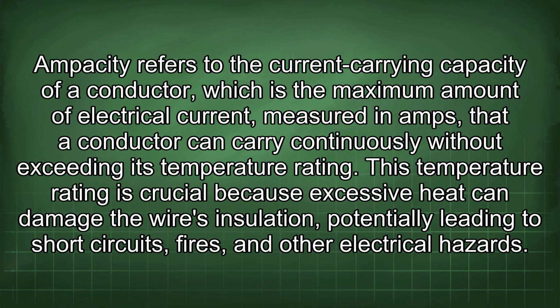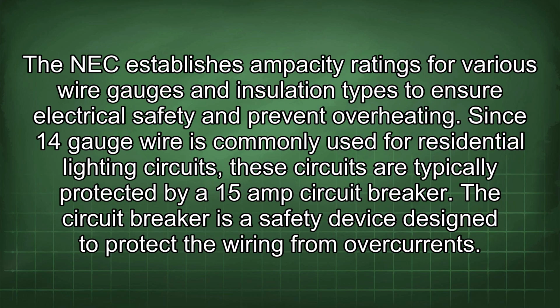Ampacity refers to the current carrying capacity of a conductor, which is the maximum amount of electrical current, measured in amps, that a conductor can carry continuously without exceeding its temperature rating. This temperature rating is crucial because excessive heat can damage the wire's insulation, potentially leading to short circuits, fires, and other electrical hazards. The NEC establishes ampacity ratings for various wire gauges and insulation types to ensure electrical safety and